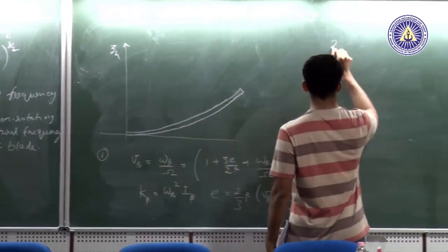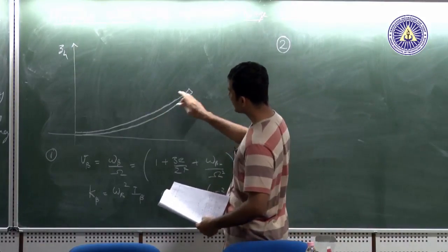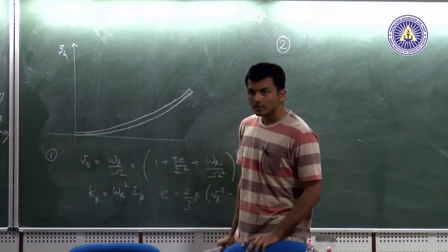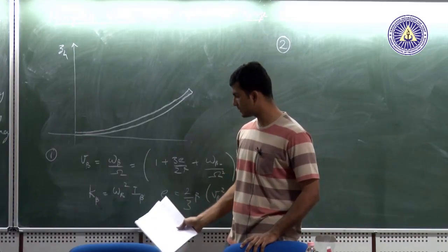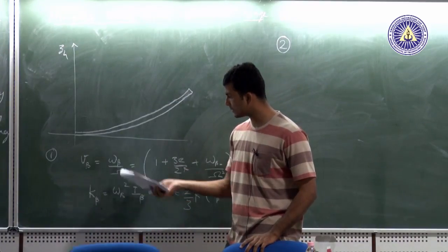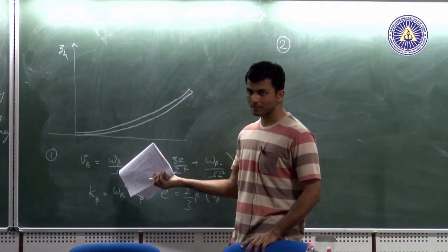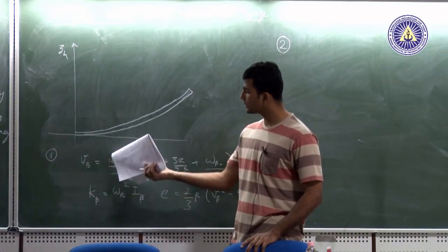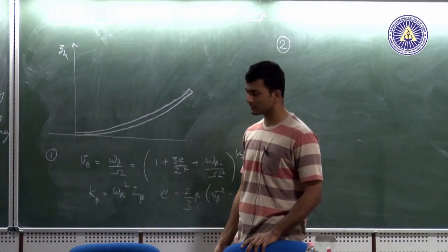Another way of doing it is by studying the bending of this blade when you give a static input to this blade. Omega beta naught is easy to get, right? And we know capital omega, right? So then directly we can get VB or whatever you are calling that. No, no, no. See, this is omega beta. They are different objects. Omega beta is your rotating natural frequency. Omega beta naught is your non-rotating natural frequency. So if you non-dimensionalize your rotating natural frequency, you get nu beta. Okay.